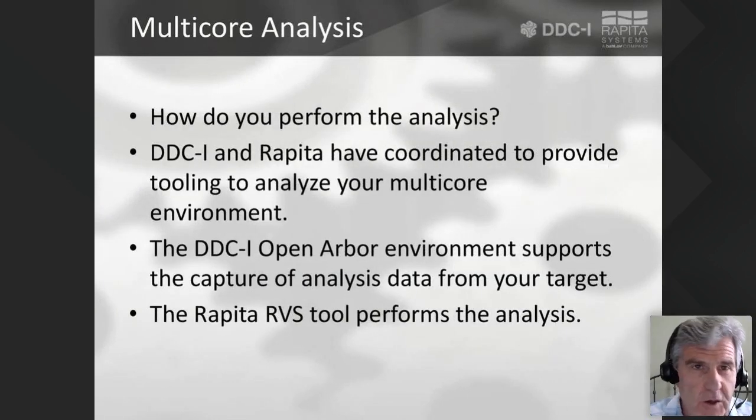All right, so you've done all your work. You have your ultimate design and your implementation to incorporate all of these features to address the CAS32A concerns. How do you measure and perform the analysis? Well, DDC-I and Rapita have coordinated to provide tools to analyze your multi-core environment. The DDC-I Open Arbor environment is configured to generate a project suitable for the Rapita RVS analysis tool. In the demonstration you're going to see, we're using a ZCU102 platform. This is a Xilinx UltraScale Plus running 4 ARM A53 cores. Here's how we get it started.